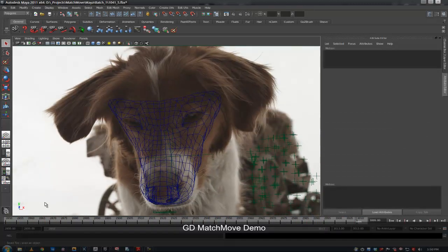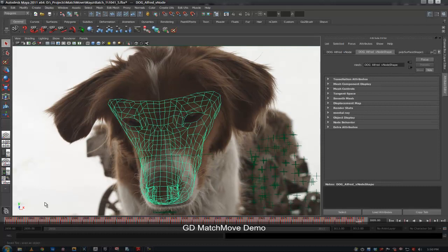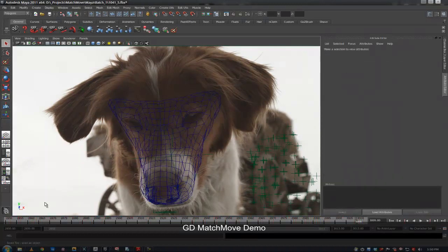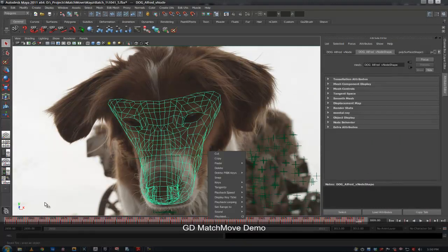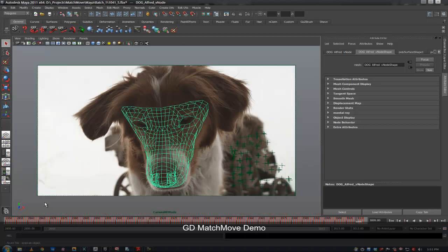I can select the mesh so that it's highlighted. This is a dark background, so I want it lighter, so I select it. If it's a lighter color character and I want it to be darker, I can deselect it. So once it's selected, I just go ahead and choose Playblast. But before that I want to make sure my entire view is seen, like maybe the points or the mesh are going off frame. I want to be able to see that the motion is right. So I'll turn on my resolution gate, and that is done.